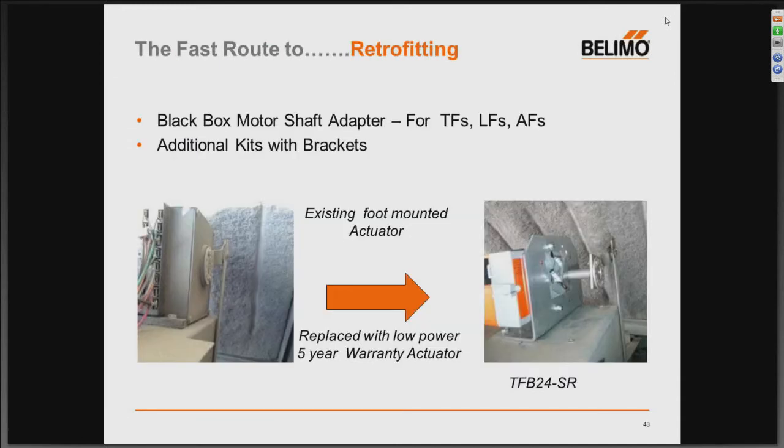Now we realize that retrofitting is a big part of this, like Kevin mentioned. And unfortunately, the majority of the time that's sometimes spent on retrofitting economizer jobs happens to be with retrofitting the actuator, just because of the older linkages that are built into these units and the fact that as soon as you tweak that linkage, everything's going to go out of whack.